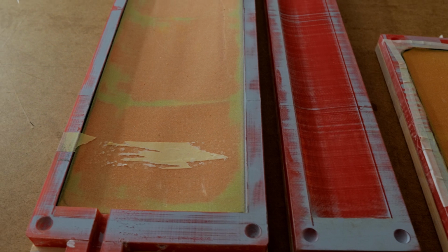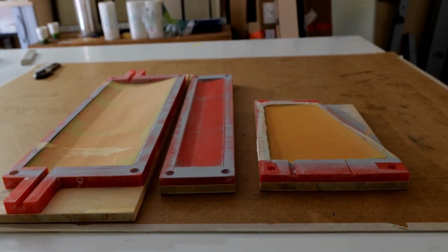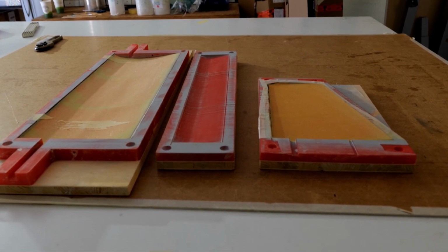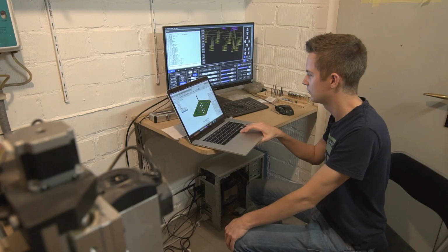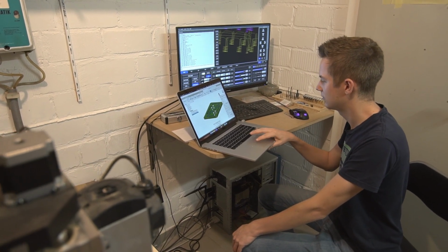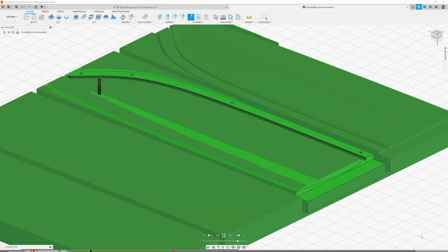First, we tried the same method of 3D printing the molds that we used for the fuselage, but this failed because the molds were too weak to withstand the pressure of the vacuum bag, which we needed for the lamination of the wing. After this failed attempt, we decided to use our CNC router to machine a new set of molds. These molds would be of much better quality and stronger than the 3D printed ones.